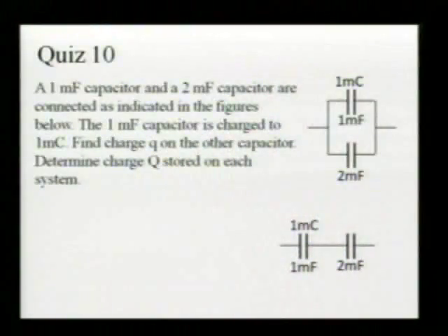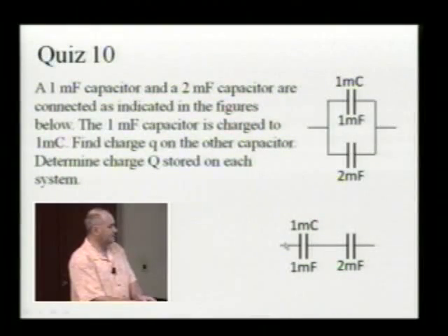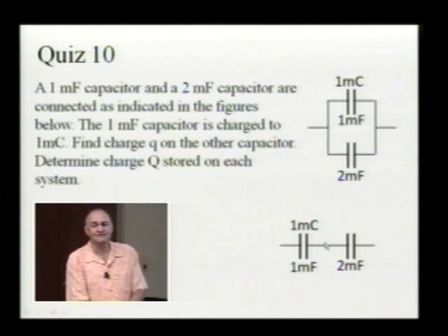All right, let's now see. The correct answer is 1.5 volts. And let's see for the reason. In order to have the potential difference between this point and this point to be 1 volt, this potential minus this potential, I want to be 1 volt.